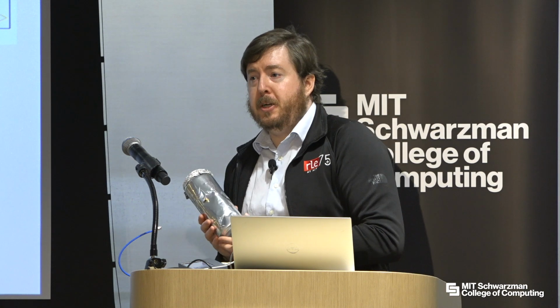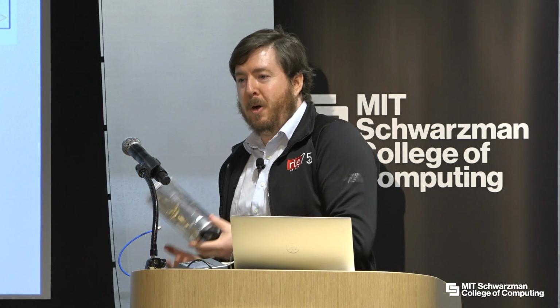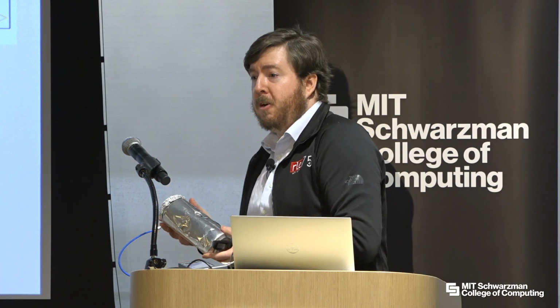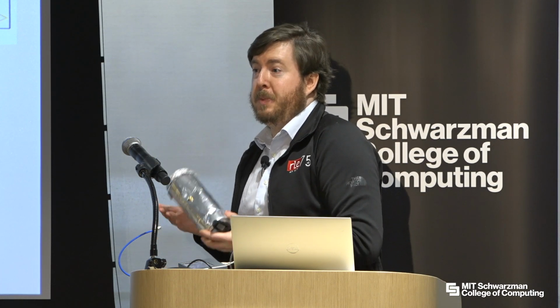So people often ask, if there are room temperature superconductors, could you operate a quantum computer at room temperature? And at least if you're operating at, say, sub 10 gigahertz, the answer is no, you couldn't, because the thermal photons would completely swamp the operation.